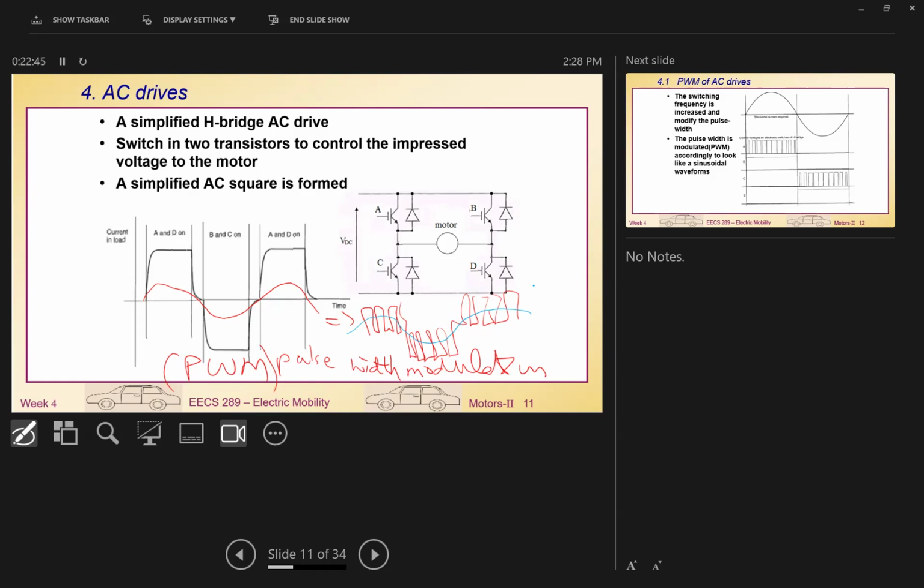The motor itself is not that careful, it only understands the average voltage. So that's good enough. So that's why we use PWM, we are able to control an AC motor. So that's why we still call this the AC motor drive system. The pulse pattern we generate is sine wave PWM modulation. We call it sinusoidal, I think you have heard about this. Sinusoidal PWM.